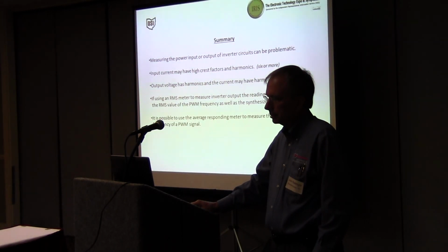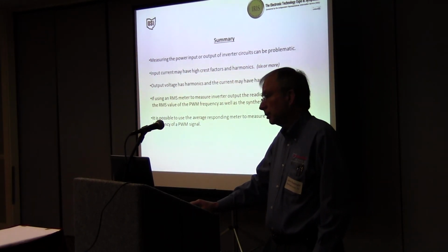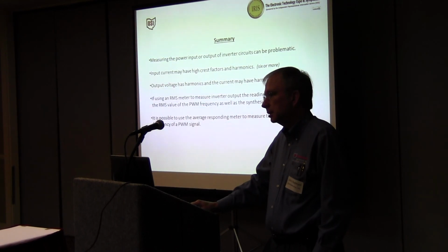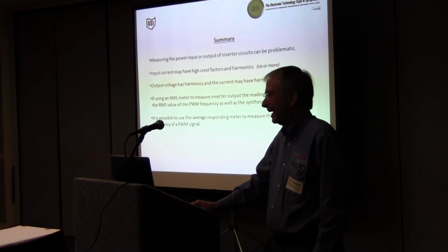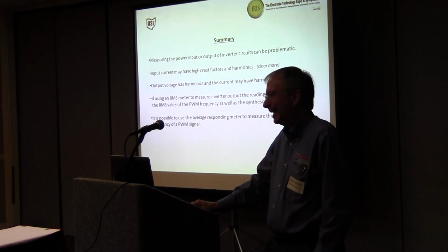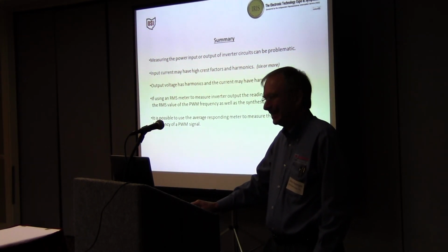That's right. You say that's a compressor? Yeah, it's a refrigeration scroll. Or air conditioning? Yeah, a unit about that big for the top of a locomotive. Oh, locomotive. Okay. Yeah, and we have to use an inverter because locomotives are DC. So we have Oztec make an inverter for us, and then we use a scroll. Just use a DC one. Tell Copeland that. That'd be easier.